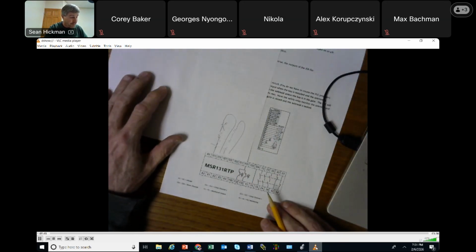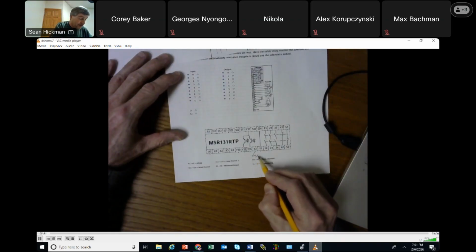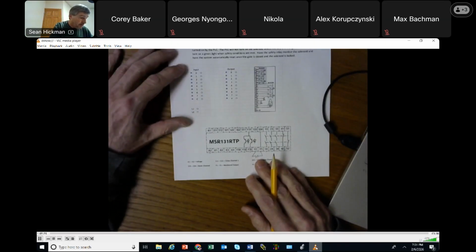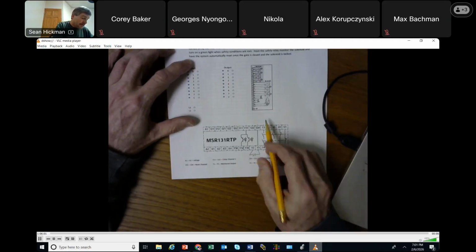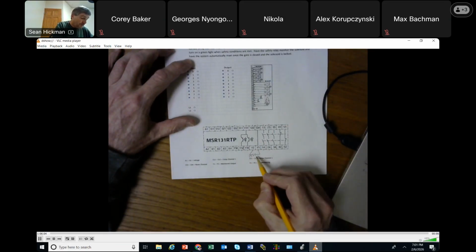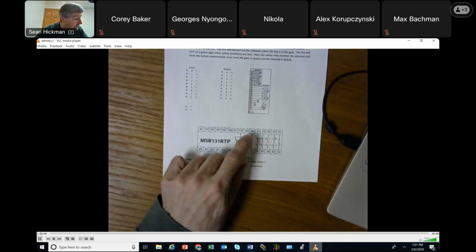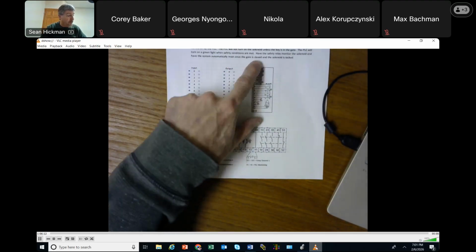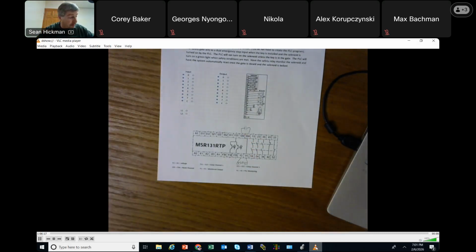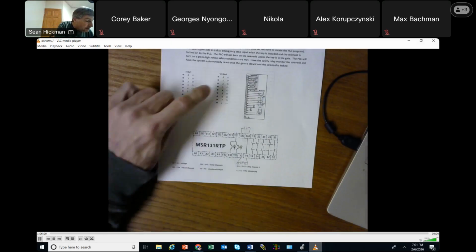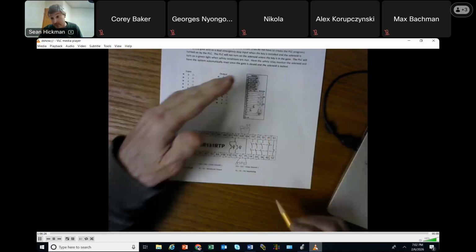It said this thing wanted to be monitored. So on my monitoring down here, I need something monitoring it. And it said, what was it? The PLC will turn agreement. Have the safety relay monitor the solenoid. So it looks like I'm monitoring the solenoid right here, 33 and 34 of this, to be sure that that's my reset. Or it says, have the system automatically reset once the gate is closed. So I can come right here, and my reset is right there. So it's going to be my 30 and my 33 and 34 here, and when this closes, that resets the safety gate.